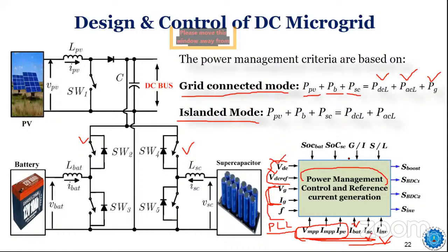Inverter control generally requires you to take more decisions based on the grid connected or islanded system, right? Whether there is too much surplus power or lacking power. Surplus power means, if the PV power is more than the load demand, or whether the PV power is lesser. So based on all these conditions, you need to develop the PWM control technique for the inverter. Then you need to control. So you see, when you develop a complex system like this, connecting more sources, power management plays a major role. So you need to develop an efficient power management controller for this type of system.